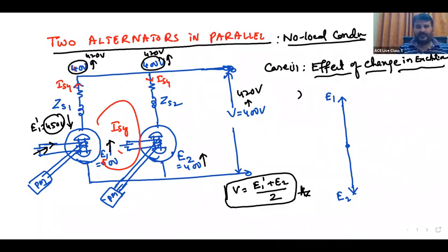See, one general statement. During parallel operation, an overexcited machine will always be demagnetized. This is a very important conclusion, not only here, but everywhere. I'm going to write all the conclusions, but first listen.